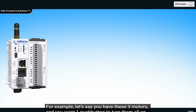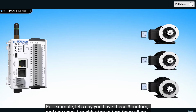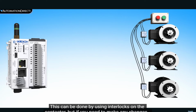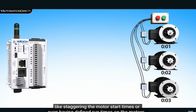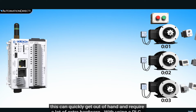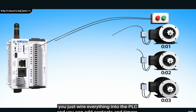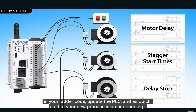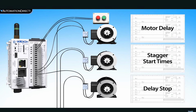For example, let's say we have these three motors and you want one push button to turn them all on. This can be done by using interlocks on the contactor. But if you need to make any changes, like staggering the motor start times, or even having defined run times on the motors, this can quickly get out of hand and require a lot of extra hardware. With using a PLC, you just wire everything into the PLC, and you can add contacts and timers in your ladder code, update the PLC, and as quick as that, your new process is up and running.